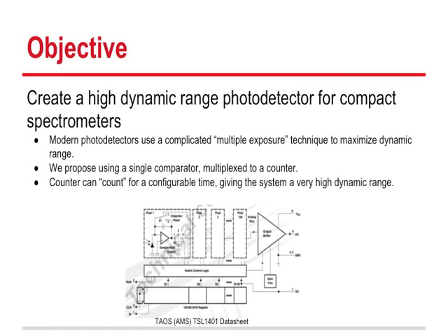The use of image sensors presents several limitations for visible light spectrometers. Both CCD and CMOS one-dimensional imagers typically use a global shutter, which is activated for a fixed time period determined by the control electronics. After the image is captured, each individual photodetector element is serially read out of the system through a multiplexer and shared charge amplifier. This process is time-consuming and also relies on an estimate of the incoming signal to set the amplifier gain and integration time to avoid saturation of the brightest pixel. This effect also limits the dynamic range of the system.